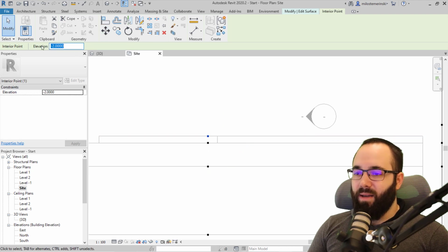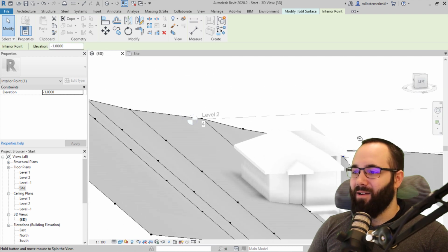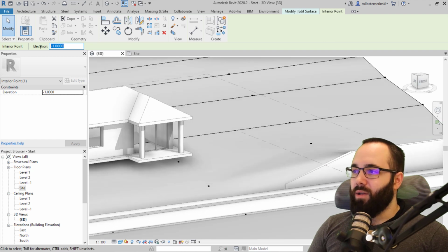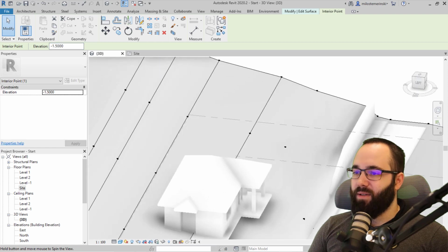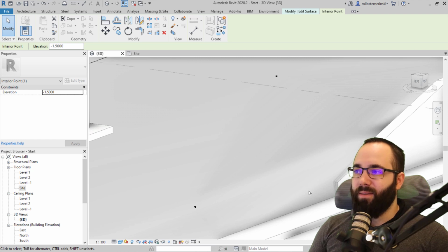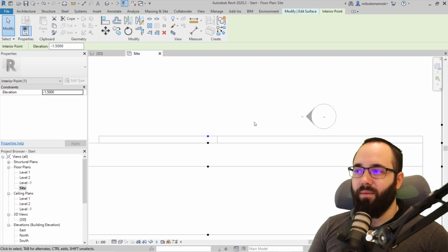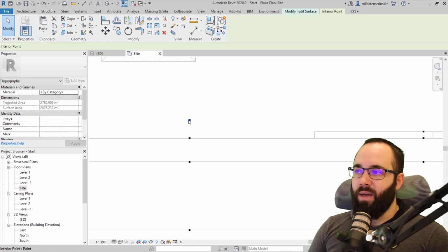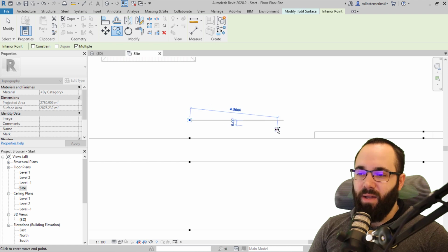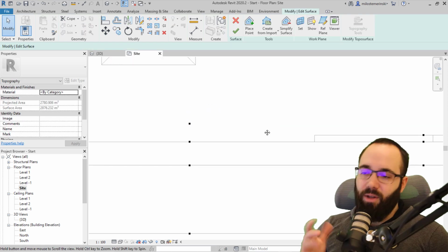Again, here we seem to have a little bit of a spillage, so let's go back here, and then we can select this point. This is at -2. So let's copy that one perhaps somewhere, or what you can do, instead of copying points, you can go to place point, but instead of absolute elevation, go to relative to surface. So what this does is when you place a point, it's just going to add an additional point at that elevation. Now it did mess things up here, but don't worry, we can fix that.